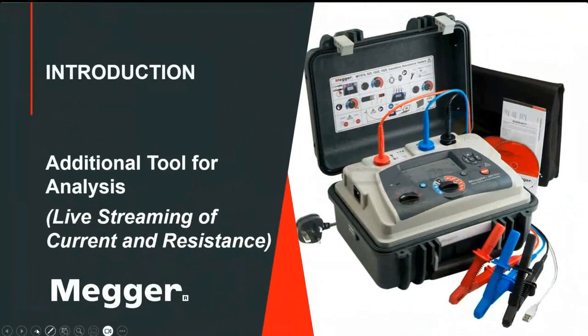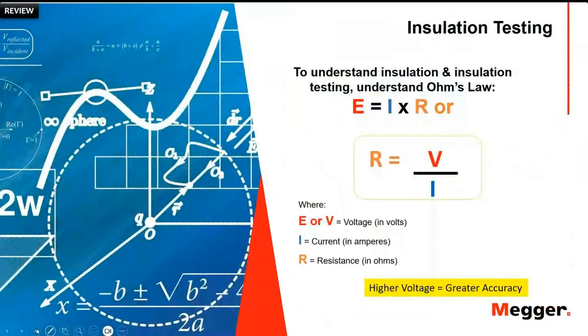Like I've said, the live streaming is an additional tool for the analysis. When you do the insulation resistance test, it is better to look at the current, what is happening during the test. This is available with our MIT diagnostic models, MIT 525, 1025, or even in the S1 models of Megger insulation tester.